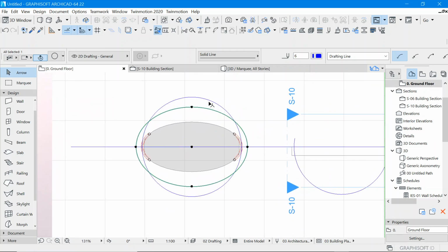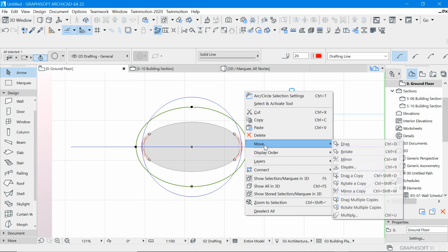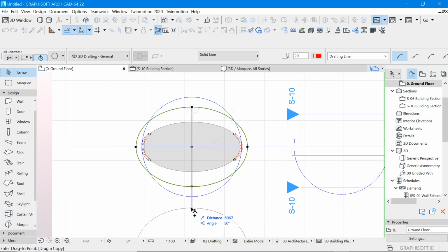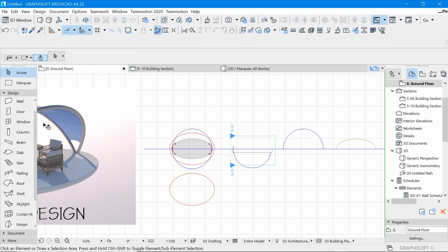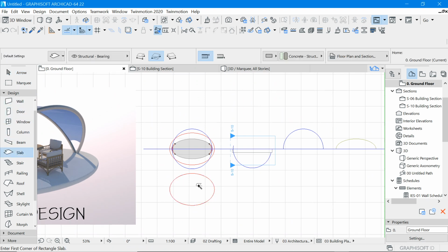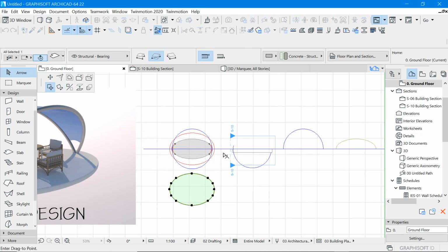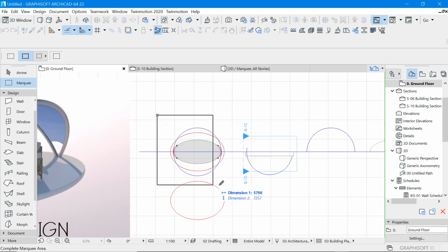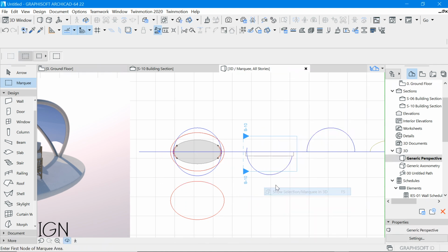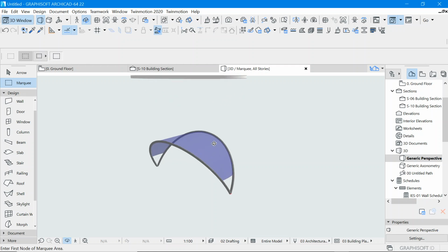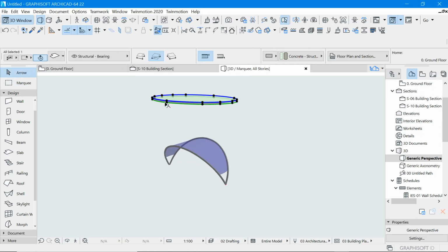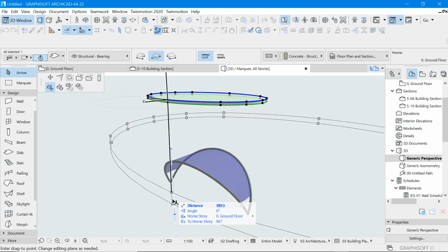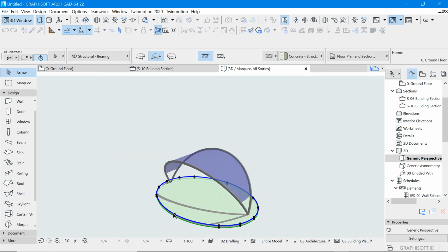Now with that ellipse, you can turn it red, drag a copy off. Now with this copy, we can insert a slab. Having inserted the slab we can take it back up. We go back in 3D mode. Once slab is still up, we want it down, click on it, pull it all the way down, can press shift to keep it straight.